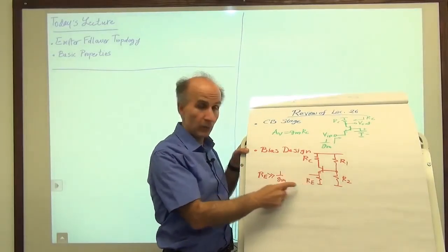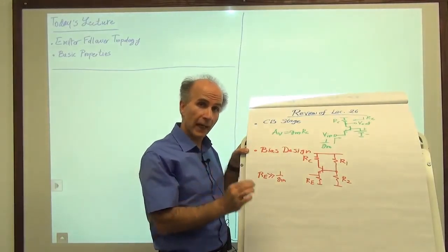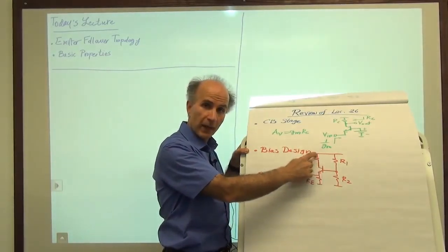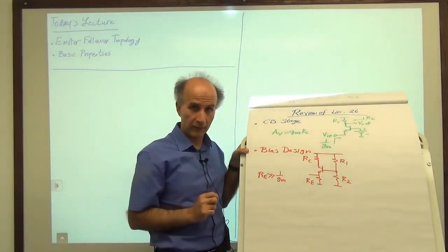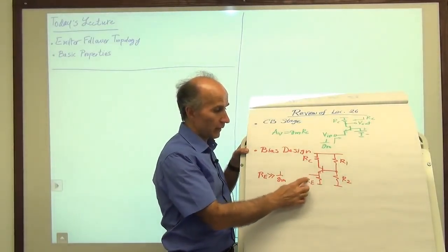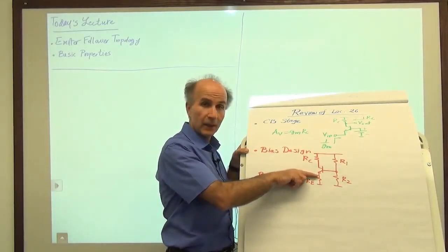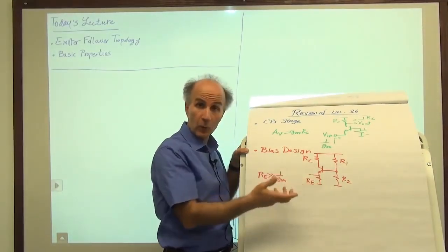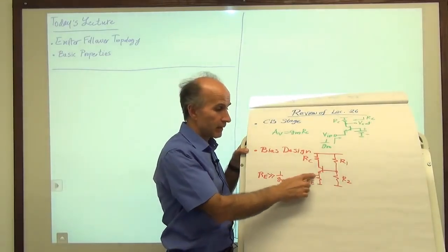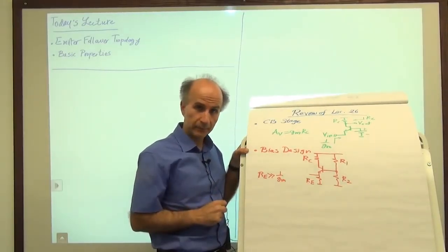Here we have used a simple resistor whose sole job is to allow the bias current of the transistor to go from the positive side of the battery to the negative side of the battery. What now happens is that RE allows some of the signal current that's coming in to be routed to ground, to be wasted. And to avoid that waste, we would like to maximize RE with some condition like this.